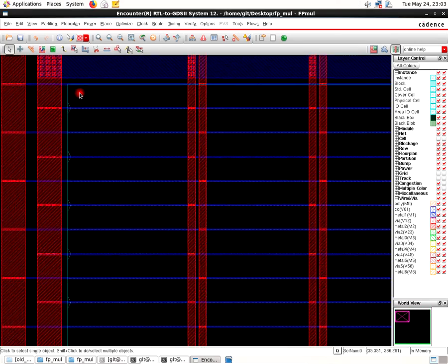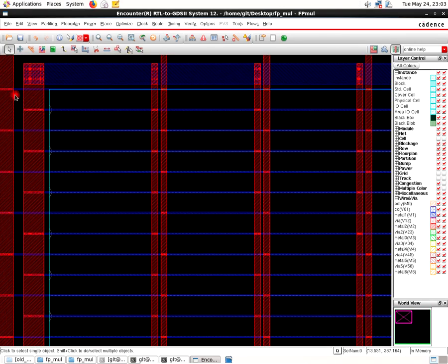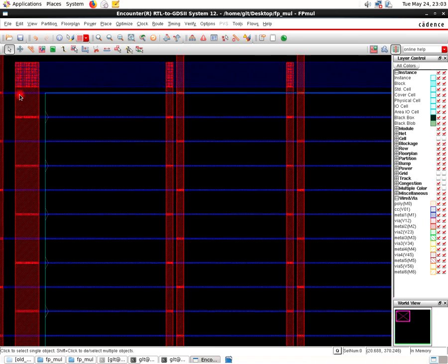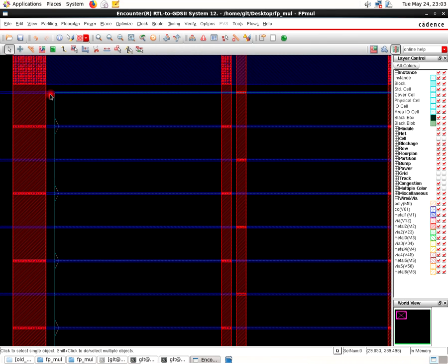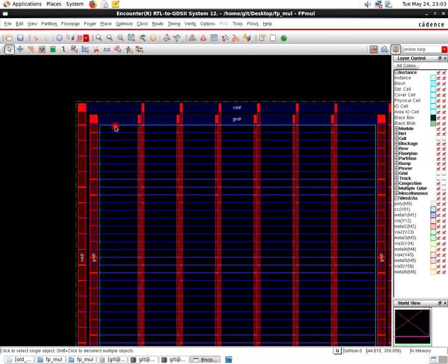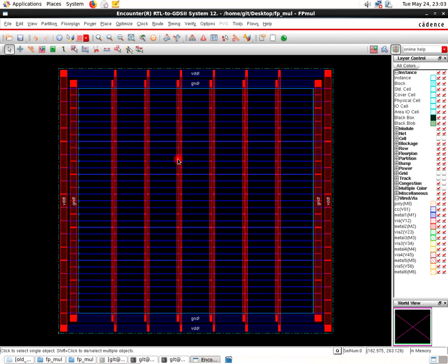See here, so this will be VDD and this is the ground. Okay, this is VDD and this is VDD and this is ground. So a particular transistor can easily access the power from these two lines. So transistors will be placed here, so it can easily access. So a drain and source can be properly and easily connected to these power lines, and the power can be easily accessed. Okay, now we have made everything clear.